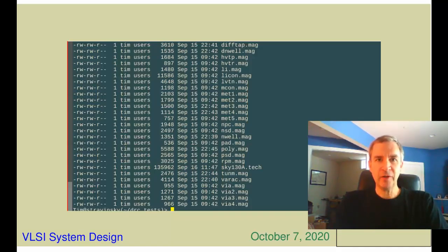To work with the full Google SkyWater PDK, you would want to get the PDK from GitHub and install it, and download my OpenPDKs installer from GitHub, and use OpenPDKs to install a version of the Google SkyWater PDK that does important things like creating the Magic tech file. But since the PDK is still under development while I'm preparing this laboratory exercise, I've instead just packaged up the current unfinished tech file for Magic along with the lab exercise layouts and bundled them into a tarball.